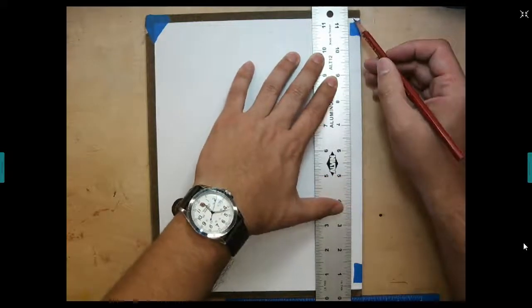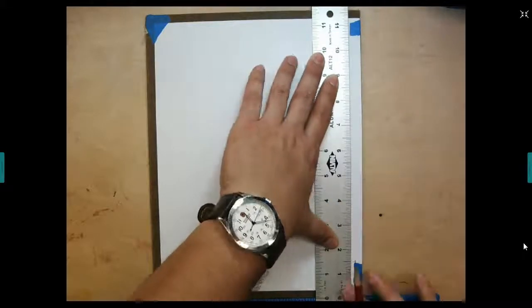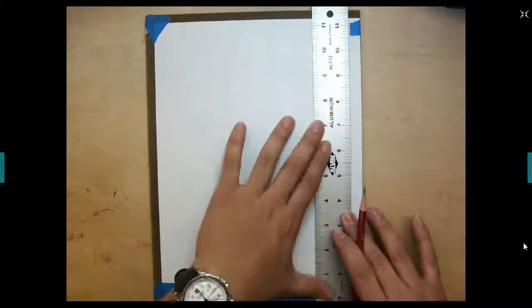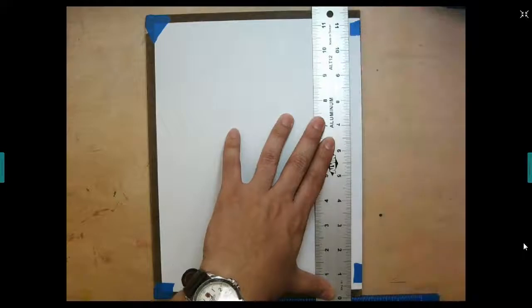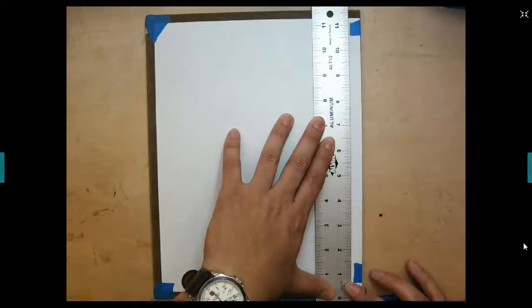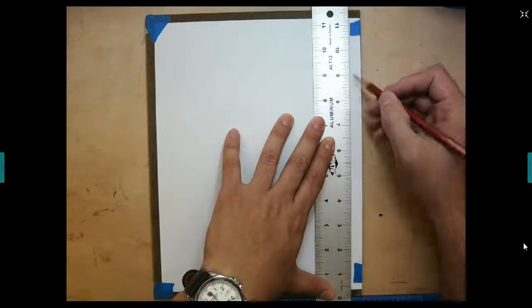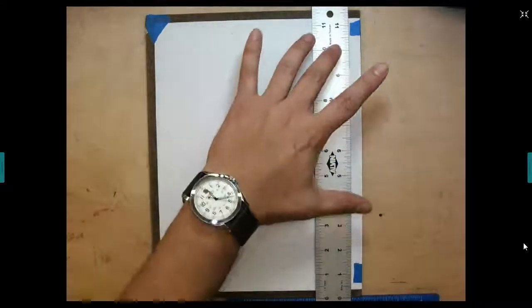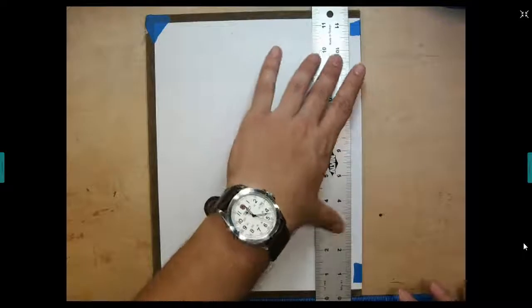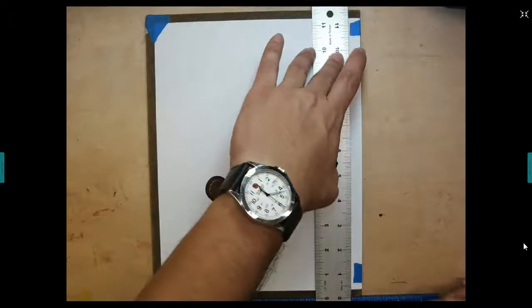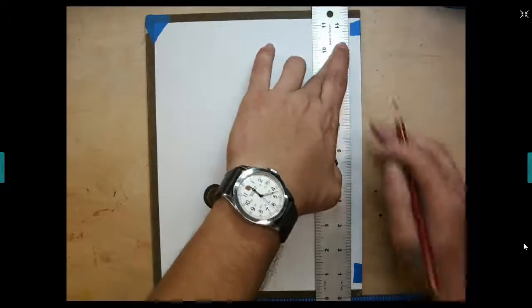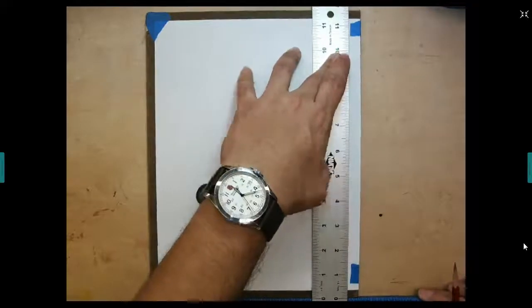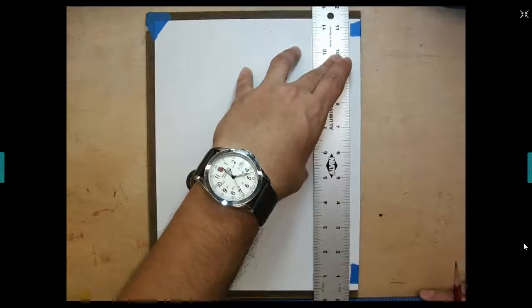So when I draw my line using my T-square, I want to focus on doing a downward motion. As I'm drawing the line, I'm going to push down on my T-square and make sure I have pressure at both ends. What some students tend to do is put pressure on one edge, and as you're drawing down, you create a pivot point, and this could pivot.